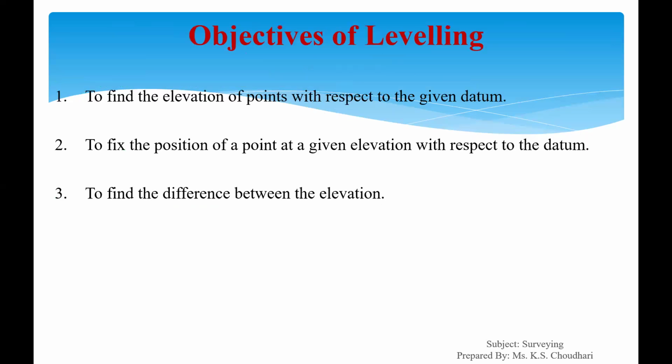Now, what are the objectives of leveling? Number one, to find the elevation of points with respect to the given datum. Number two, to find the position of a point at a given elevation with respect to the datum. Number three, to find the difference between the elevations.